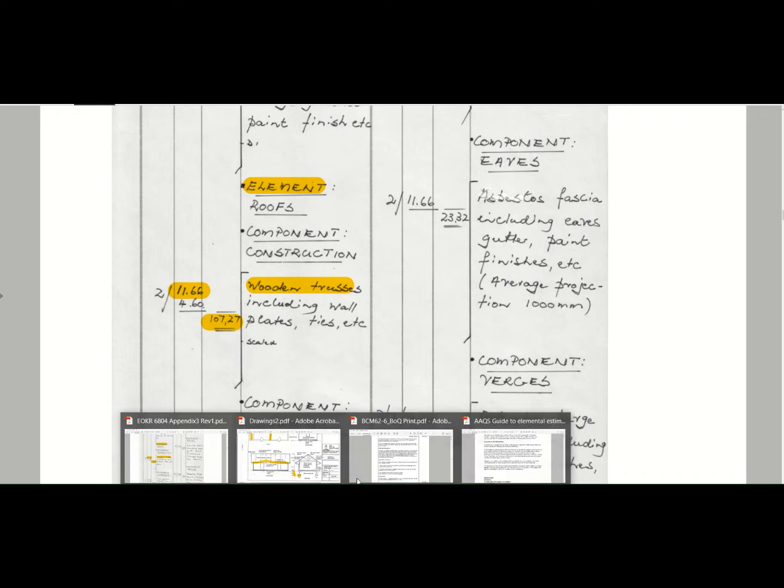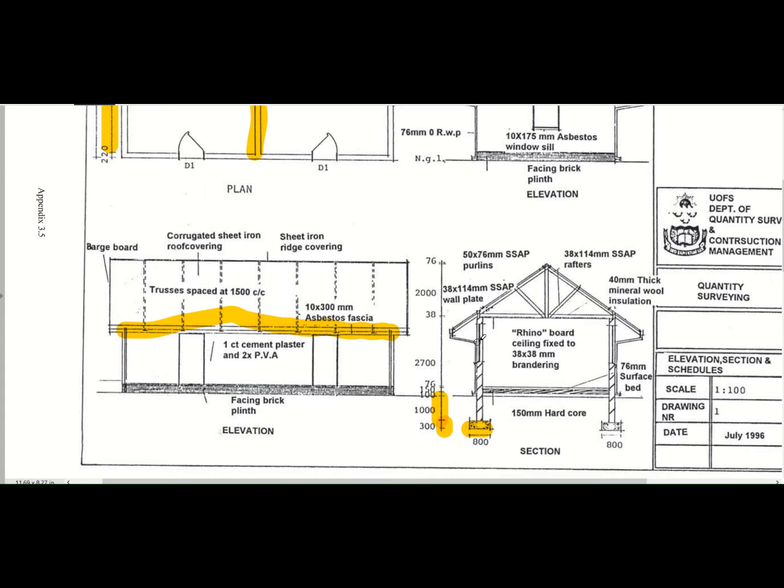If you've got a previous drawing that you measured differently in your bills, your roof area is usually measured over the angled roof area, whereas many times you might have a roof that's measured over the flat area.